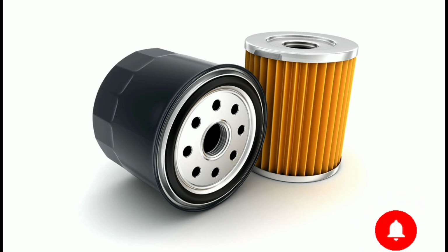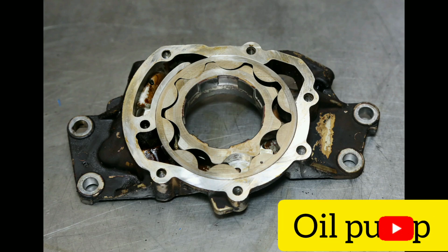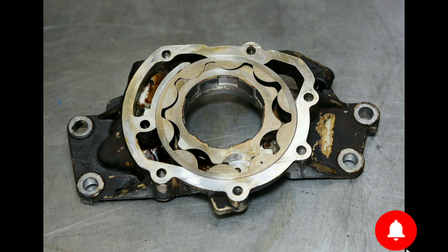This is an oil pump of an engine, and as you see, this is a gerotor pump type. In the next videos, we'll explain the different oil pumps used in a hydraulic system, but mostly the oil pumps used on car engines are what we call rotary pumps, or gerotor pumps. The purpose of the oil pump in an engine is to generate the pressure needed in the lubricating system components. It draws oil from the oil pan and sends it to the lubricating points of the engine. An oil pump carries oil from the oil pan to the important components of the engine that need lubrication.